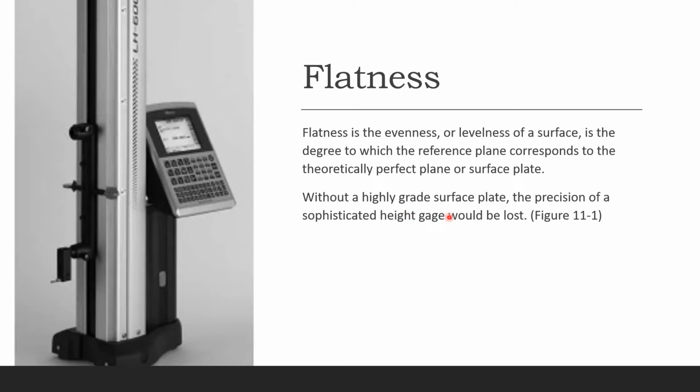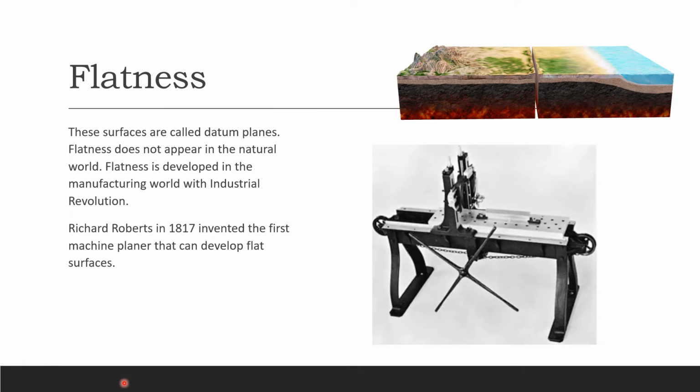If you don't have a good surface plate to put your part on to measure, even if you have a really good height gauge, you're gonna lose accuracy and precision, whatever sophisticated instrument you would use. So the flatness of your surface plate is incredibly important.